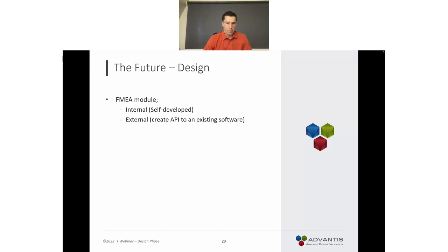A lot of people get confused with risk assessment and FMEA, and say, I do an FMEA, I don't need a risk assessment. But people that know understand that FMEA is really just the verification of an existing design. You need to have a design in the first place. It does not replace your risk assessment. It's a different thing.